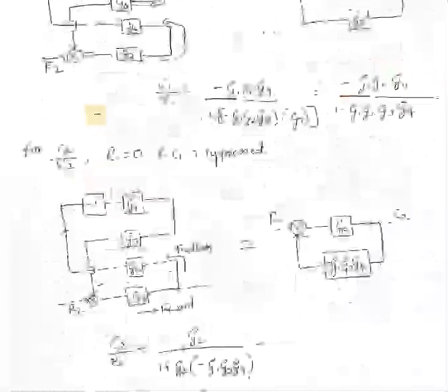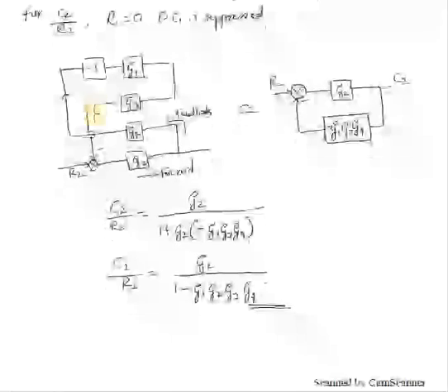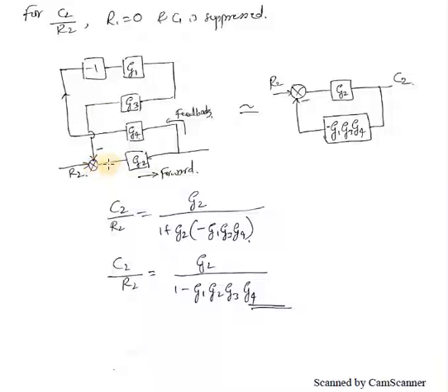And then you need to carefully observe which is the forward path and which is the feedback path. Based on that, you will get the series combinations. Finally, you will get the canonical form, and you have to write the transfer function for that canonical loop. So these are the problems on multiple input and multiple output systems.